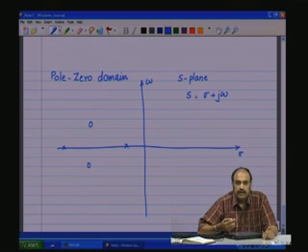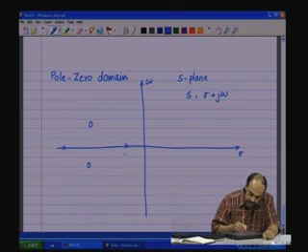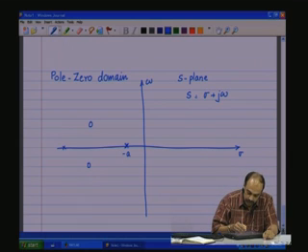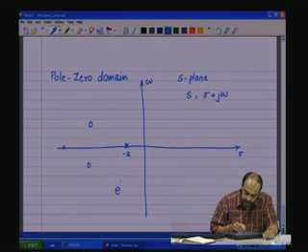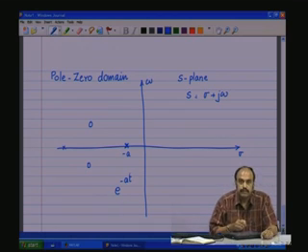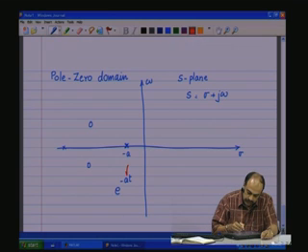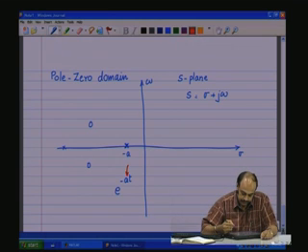in the time domain, the exponential behavior, that is e to the power of. That is, if there is a pole of value a only, then this will result in a time response of e to the power of minus a t. So, we know that if there is a disturbance in the system, that disturbance will decay with this time constant, a time constant which is 1 by a.